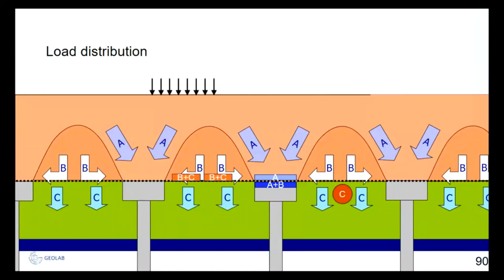It's very important to calibrate the pressure cell for decreasing load if you expect decreasing load. So you always have to calibrate each instrument before installing it, and best to try a load that you expect in the experiment. And if it is decreasing, use decreasing load. Theoretically, it should give the same result, but it is not always the case.